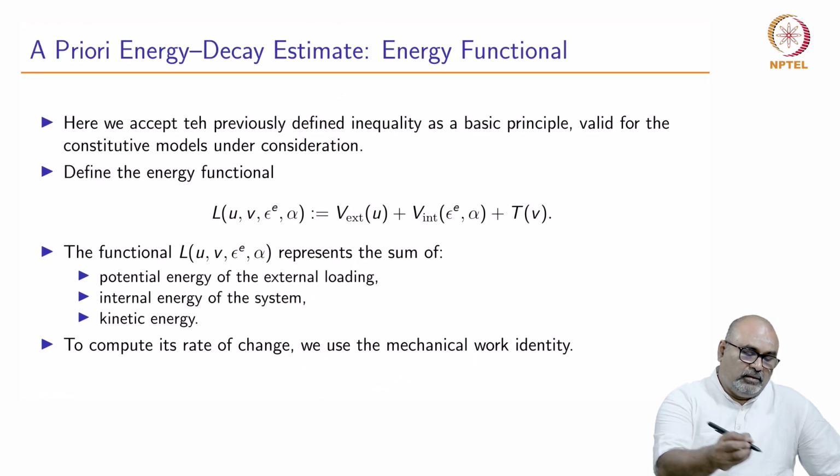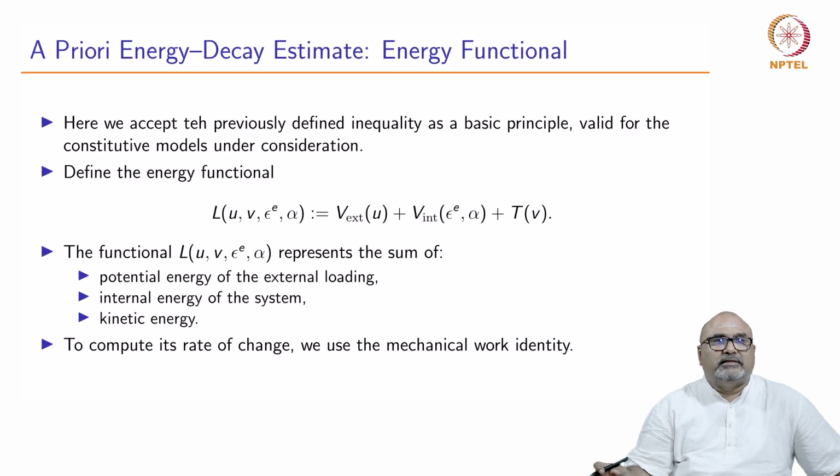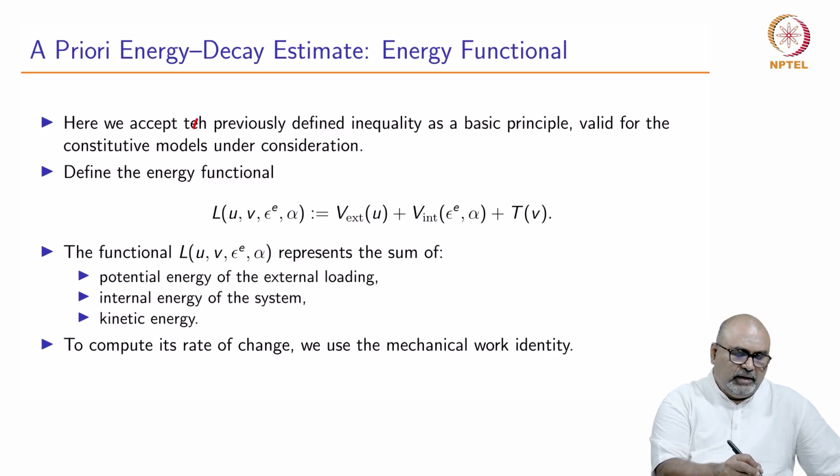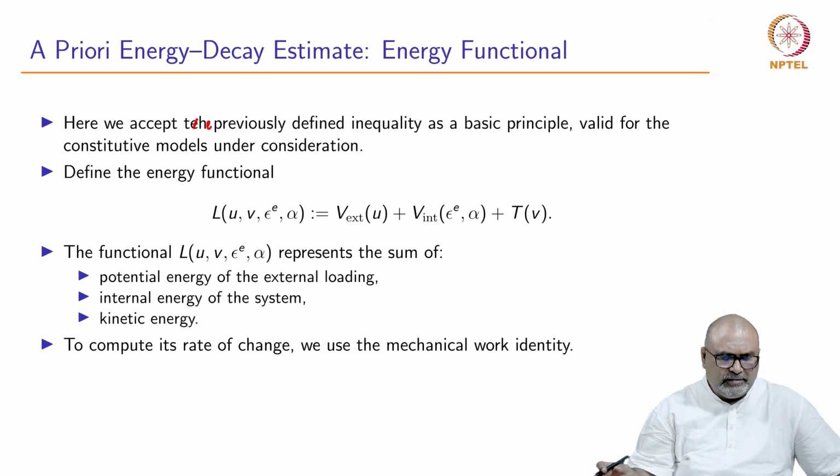So, an a priori energy decay estimate can be made based on the energy function. The previously defined inequality, as a basic principle, is valid for the constitutive models under consideration, and we define the energy functional as L of u, v, epsilon e, alpha, which is defined as V external plus V internal, V external being a function of u and V internal a function of epsilon e, alpha, and T is the work done due to the forces as T of v.